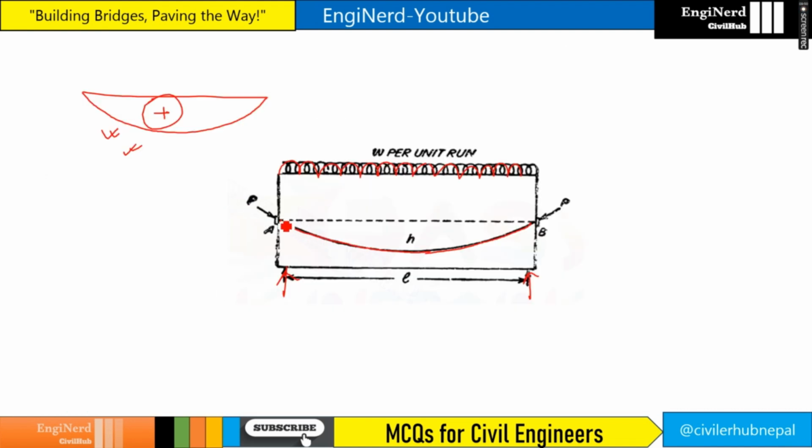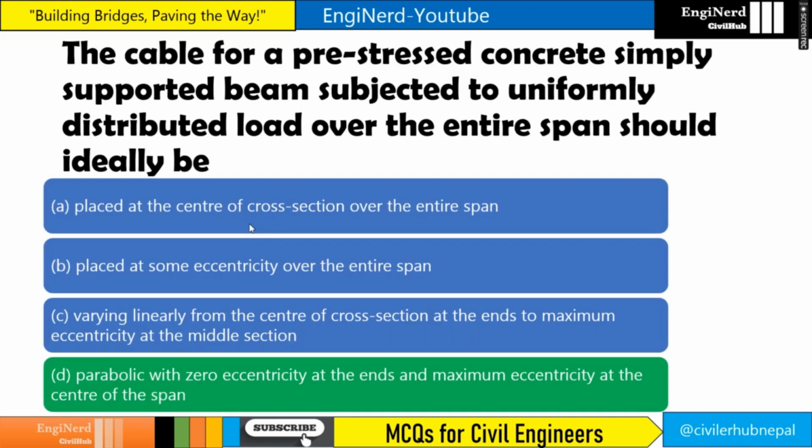Let's see, here is zero eccentricity, right? From the centroidal axis, zero eccentricity, and here is the maximum eccentricity, and again here is zero eccentricity. So it's parabolic in nature, so we can say parabolic with zero eccentricity at the ends and maximum eccentricity at the center of the span is our answer.